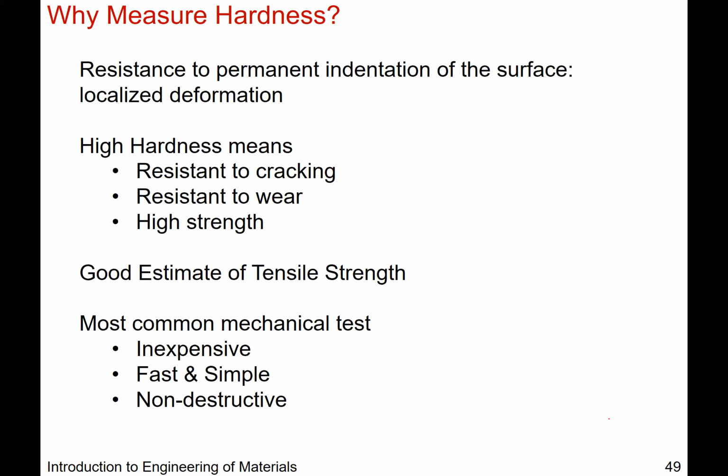It also used to be that you could take materials of different hardness values and scratch whatever it is that you're testing. If it's resistant to that, then it's harder than whatever material you had. So you used to lug around a little box of materials with known hardness. Obviously, that's very qualitative, but you can now do standard hardness measurements.